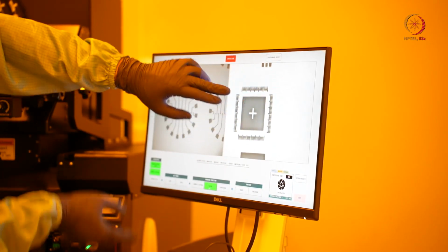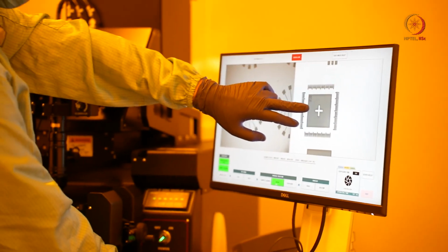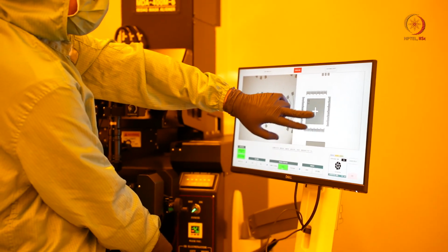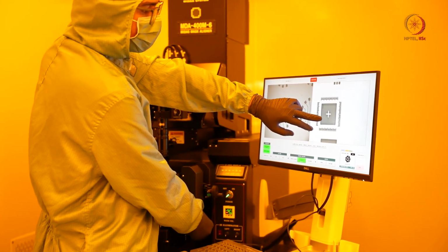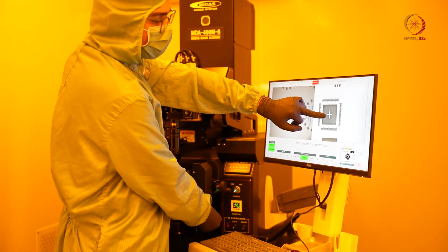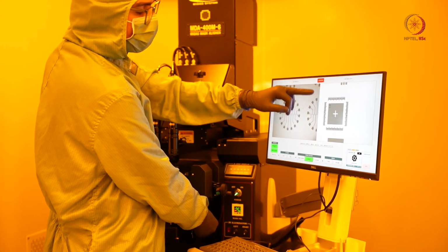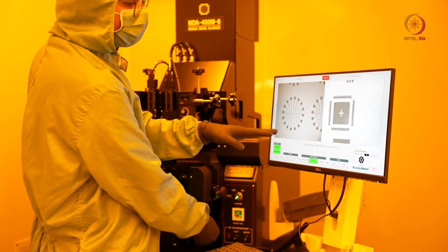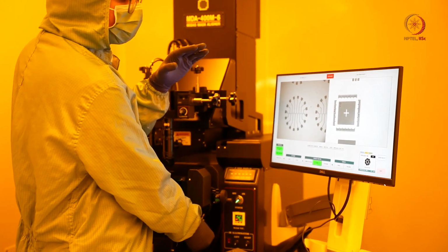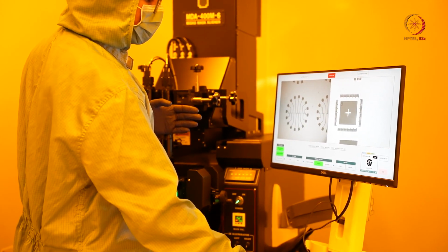When you move it closer, you can see the... I am slowly lifting the wafer up. And you can see that there is a change in shade. Now that area has also focused clearly. If you look here, you will be able to see the shadow of this plus mark very slightly here. But once you bring the wafer close enough, that shadow goes away. That means both the mask and the wafer have touched now, but we don't want them to touch. So for that, now we will do the wedge lock.